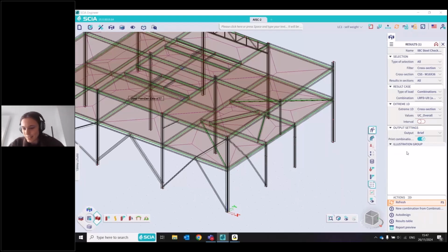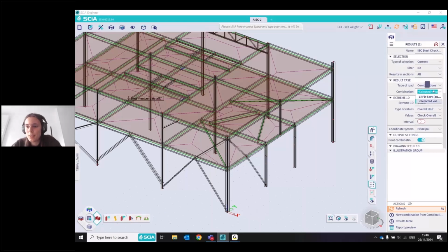Wow, time really flies. I thought this would take me half an hour or something, and here we are 48 minutes later. The final thing to look at is probably the serviceability check. Nothing really particular there. You can, of course, choose the serviceability type combinations. If there are no combinations to select, it's because you haven't defined one. There's a smart filter here so that you cannot choose an ultimate type combination for executing a serviceability limit check.